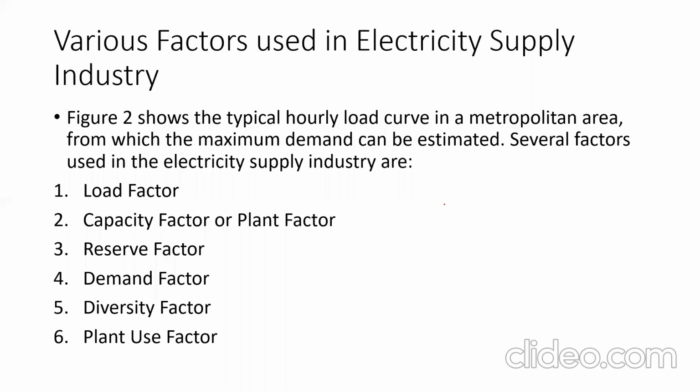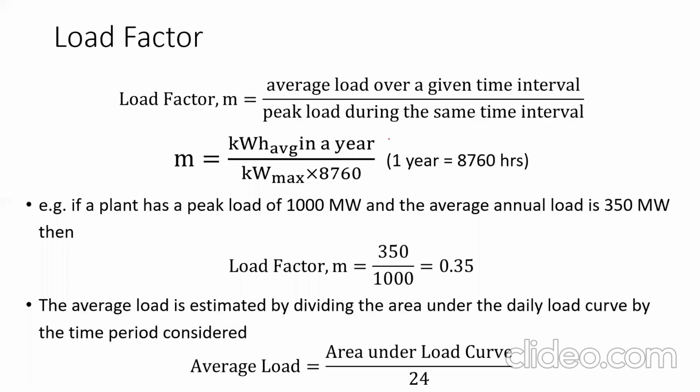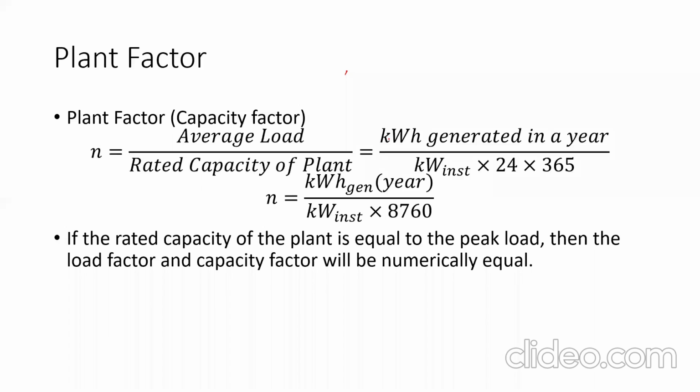I said that load factor is equal to capacity factor when peak load is equal to capacity. The numerator of load factor and capacity factor are both the same, but when the denominators become equal, then those two things will be the same. That means, when peak load is equal to capacity load.